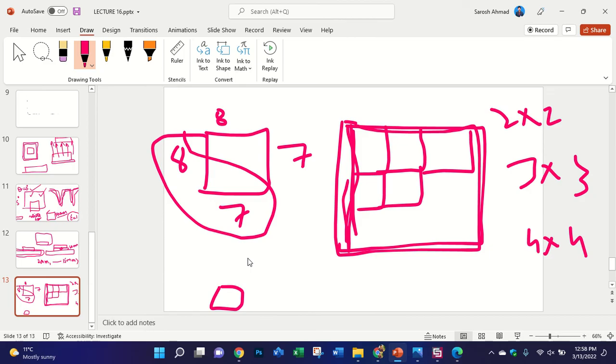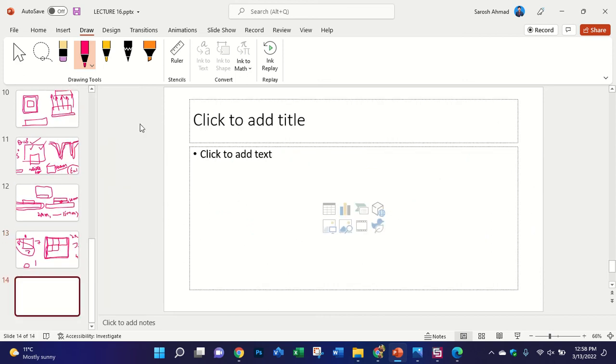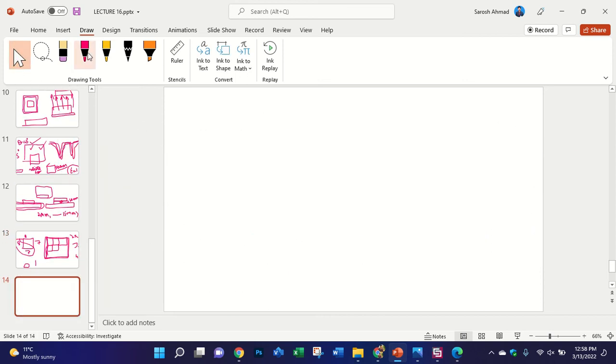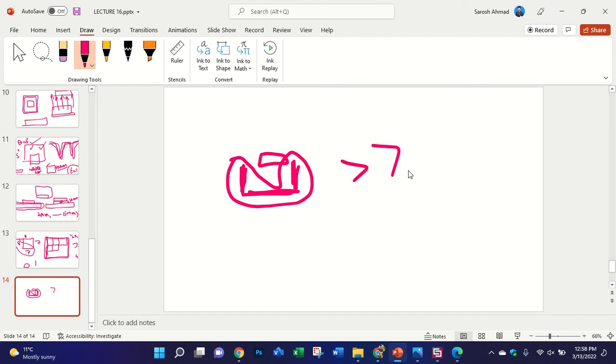This is his antenna layer, very small size, and this was the circularly polarized antenna, and he used the 3D box, maybe as a metamaterial, on these sides and then on this side, in a different way, and he achieved a gain at the lower frequency band of more than 7 dB.